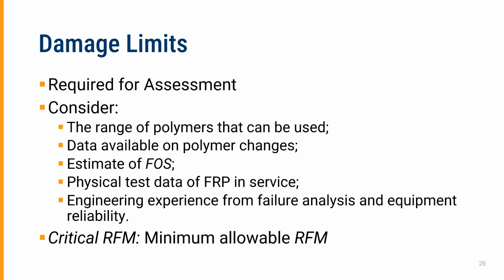The estimate of the factor of safety of the equipment. We'll talk about that a little bit in a minute, but the original factor of safety that was used for design would be nominally 10. But if the installation has pressure management problems, or loads are not as stipulated by the design or assumed, or we have an effective loss of thickness or a reduction in available structural thickness of the material, then that will change the effective factor of safety.